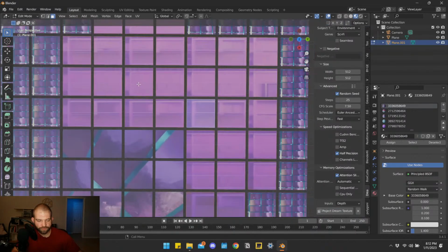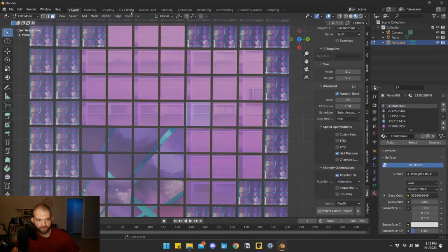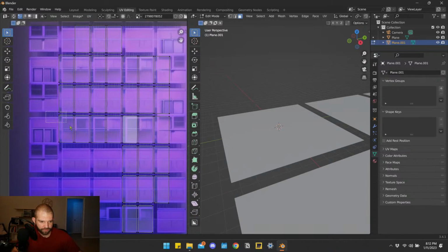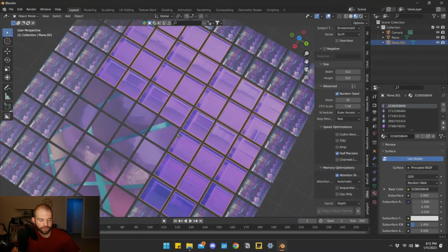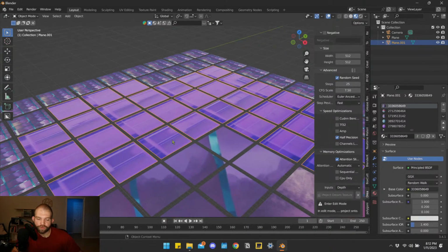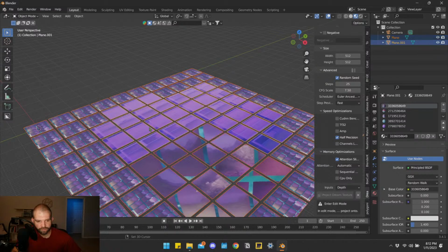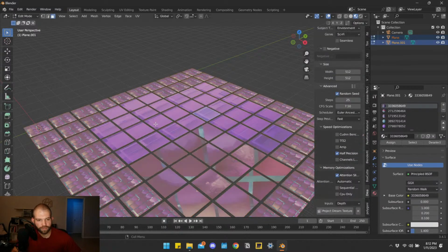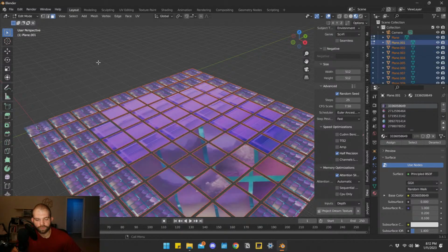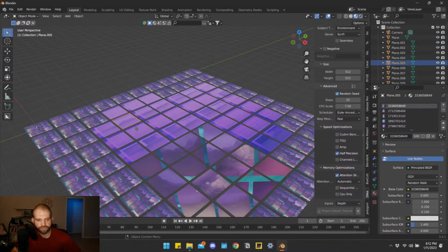All right, so we start getting what looks like the facade of a building. I'll go into the UV and we see, yep, that's actually the facade to a building. I think there has to be a bit more information in for the model. So what I'll actually do is select all of these, hit tab, and then right click, separate by loose parts, so that I'm now actually able to use all of these as separate objects.